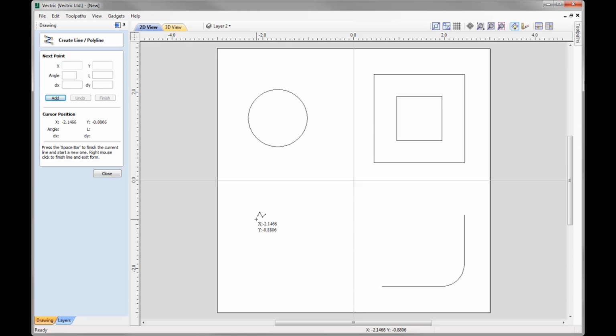So in order for us to start to draw where we align our drawing to an existing object, we need to wake it up. So to wake up an object, we simply run our cursor over the object that we want to wake up, and then we will be displayed with various lines and extensions based on the object that we woke up. So let's have a look at the shape in the lower right hand corner. So I'm just going to run my cursor over that to wake it up, and then I'm going to move the cursor away, and I'm just going to randomly move that around, and you'll see now that we're displayed with a blue line running vertically through the center of the object.